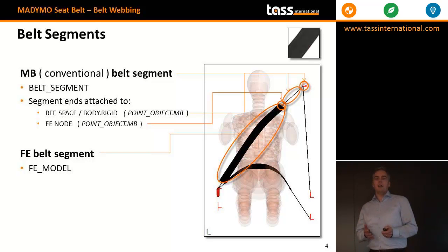You will see the switch sensors that detect certain threshold levels, and you see a switch logic that will make sure that initially all the sensors are true, and as soon as one of them becomes false, the switch logic becomes false. And in this example with a joint modeled, you have a state joint and the joint will be locked. So this is an example of how you can explicitly define your sensors in your model.